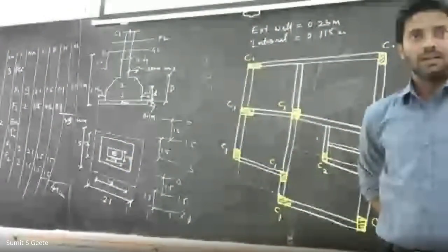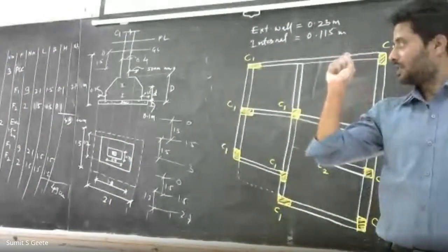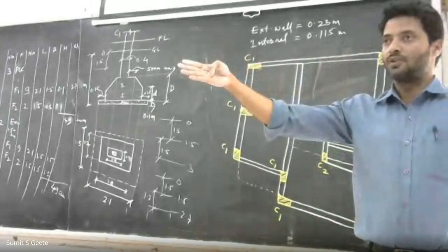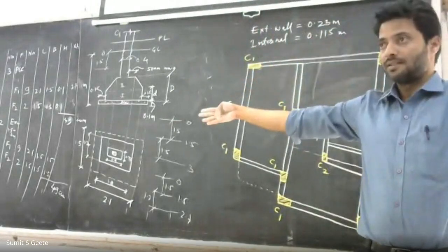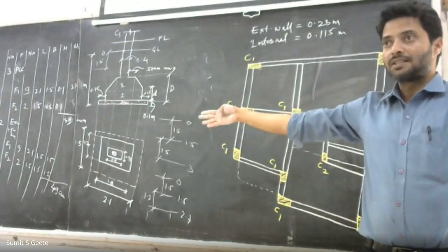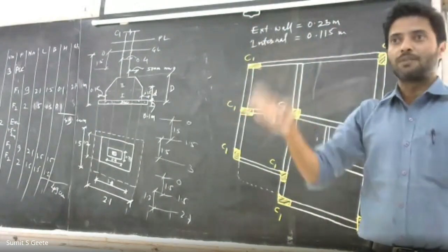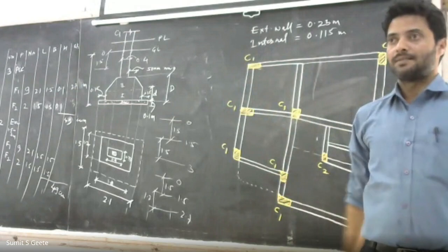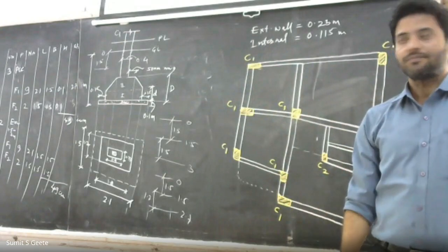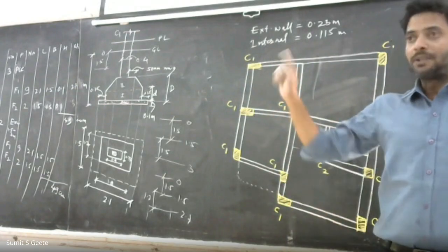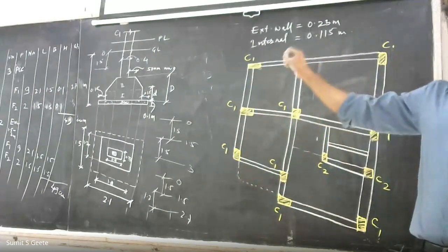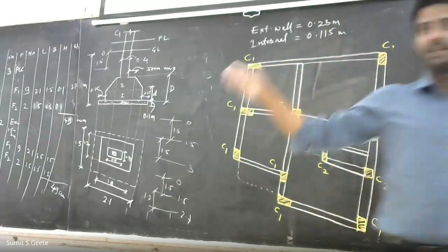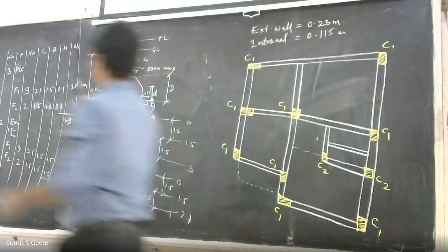Clear? तो उसमें दो कंस्ट्रेंट है. If you are giving the permission that size of excavation increase कर लो, तो strictly warn करो कि PCC को उतना मत करो जितना आपने एक्सकवेट किया. In that case, restrict your PCC to the size. Clear? चलो next. अब फोर्थ पैरामीटर इसमें हमें कैलकुलेशन लगेगा, that is the calculation of footing RCC. Fourth one is calculation of footing RCC.